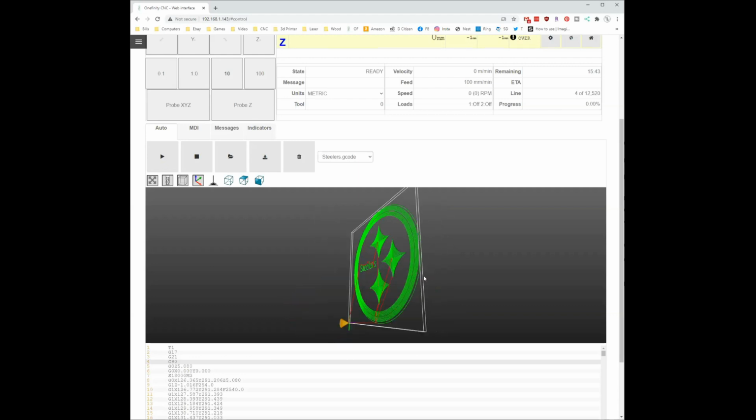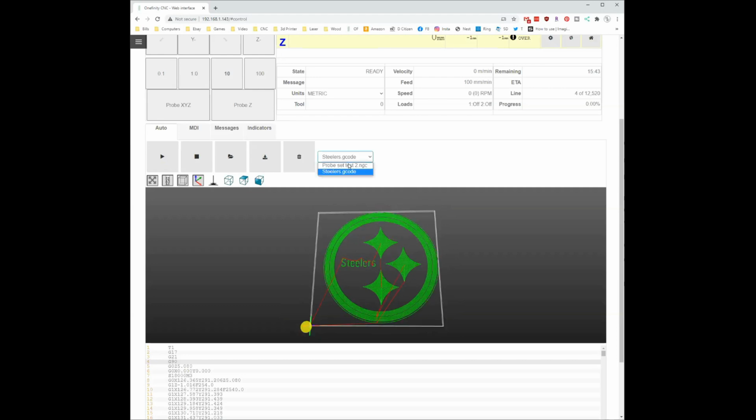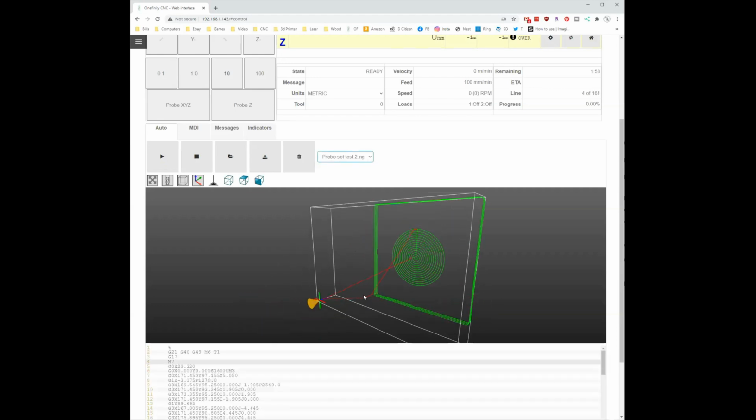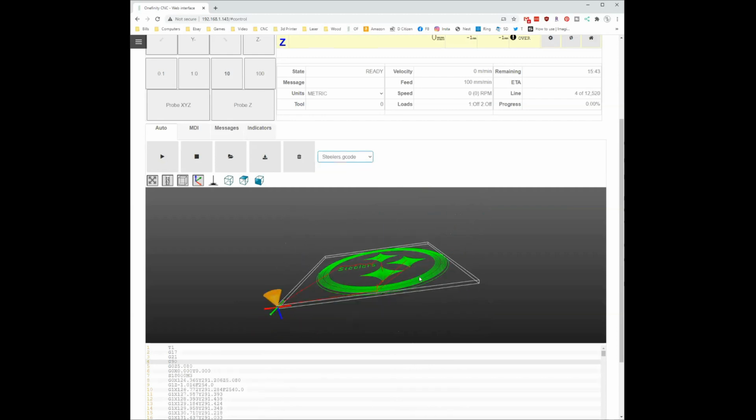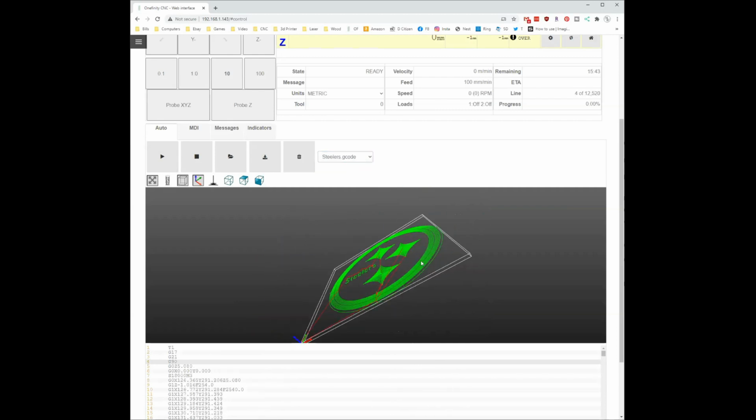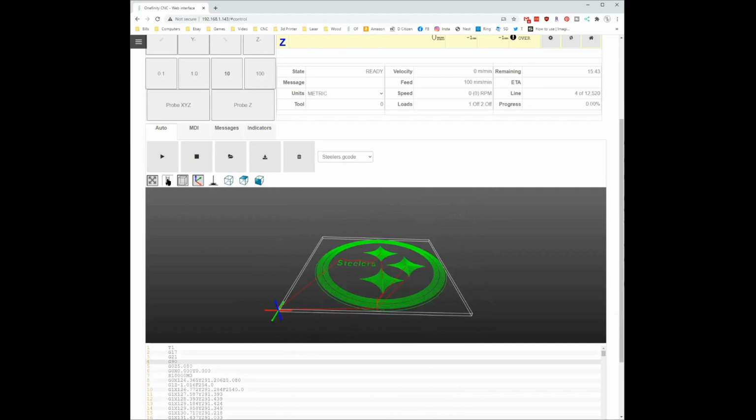So if you want to see what each file looks like, you need to go onto your computer and log in and see it. But each button, like this button here, shows the end mill, which is just a cone. When I'm talking about zeroing Z, I want the beginning of this file, where my bit is going to start, right down here where this cone is.